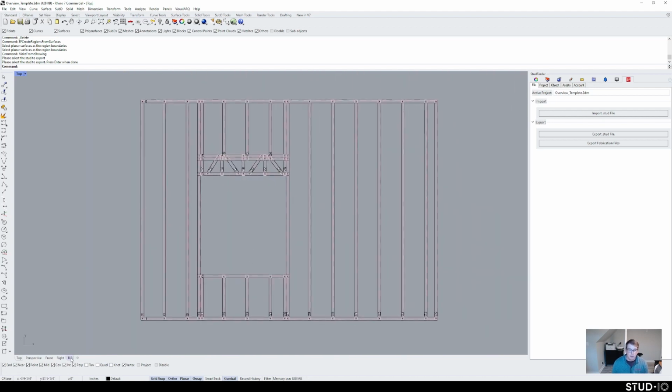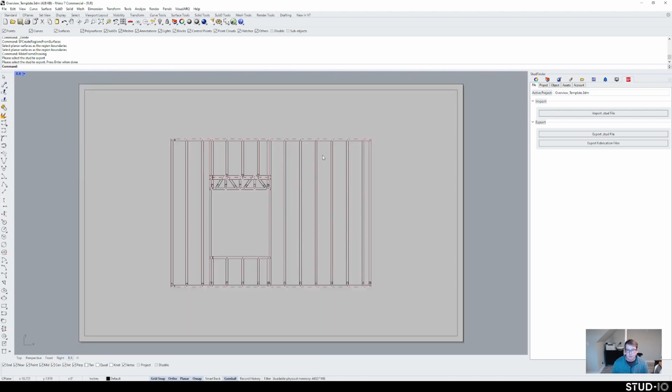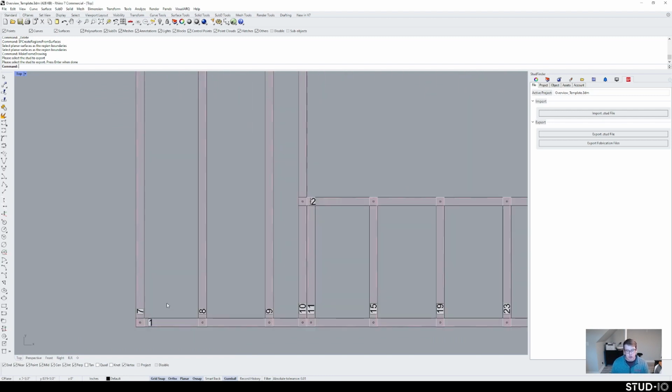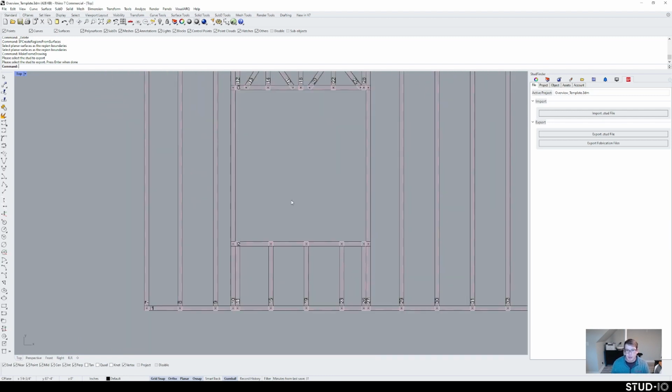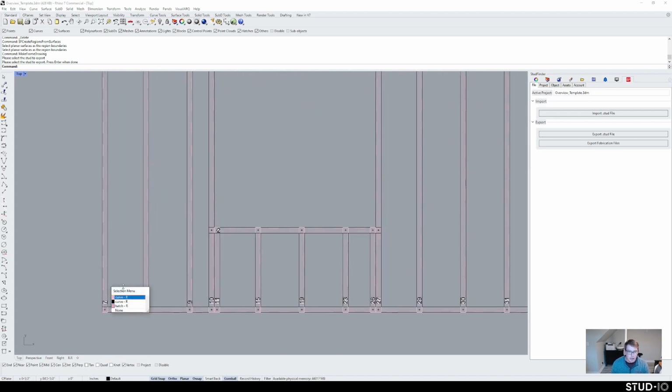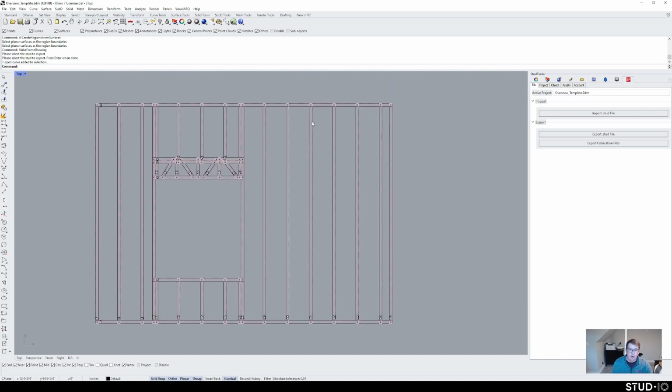This frame drawing is centered on our layout, so if you had a title block or something like that, you could quickly add that and then hit print. Labels show up, so it labels every stud that is in the drawing. It puts dashed lines, which represent the hard side of the stud, so the web of that stud. And this will match the output of the machine.